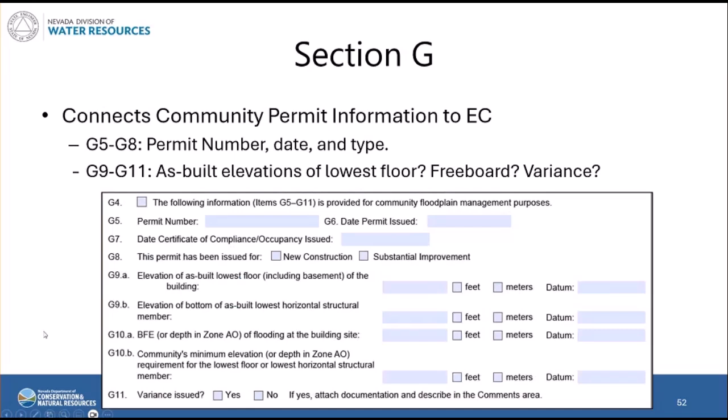If there's an error in section C of the form that the surveyor or professional engineer made, it's important to just send that elevation certificate back to the surveyor to have them correct it and send it to you on a new form. C and D have to go back to the certifier to redo.